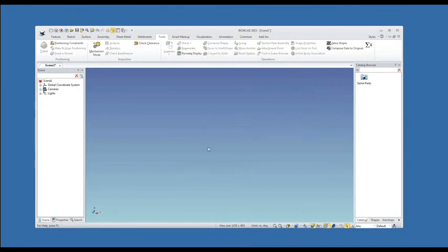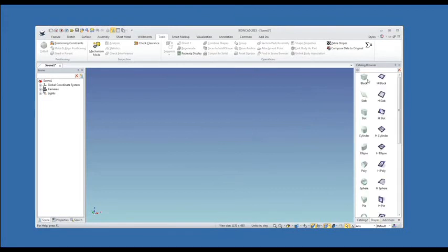And we'll start with a new example, because I want to show off parameters, because parameters are a nice way to kind of tie the attachment points. Like say, for instance, you drag and drop a part out and it snaps together, but you also want it at the same time to acquire a certain parameter based on what it's dropped upon. So for an example, I have a shaft here, and I'm about to have a hole in my block. So say my hole is 3/8 of an inch. Oops, 3/8 of an inch. And let's just make it all the way through.